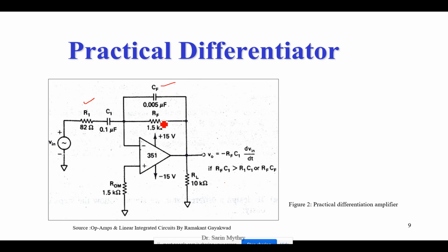I was telling you many times in the class regarding how to increase the gain of amplifiers in different ECAD software, like PSpice which you are working with right now. I told you to check what could be the value of a particular resistor or capacitor which is going to have the greater influence on the output.